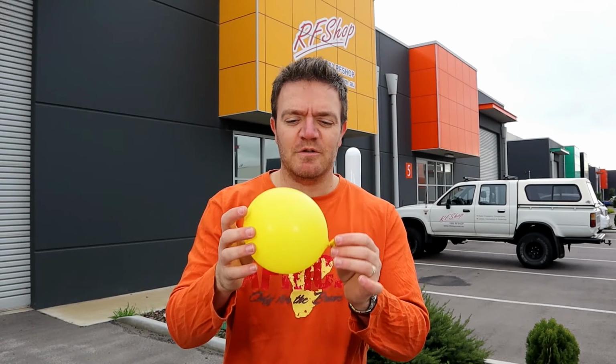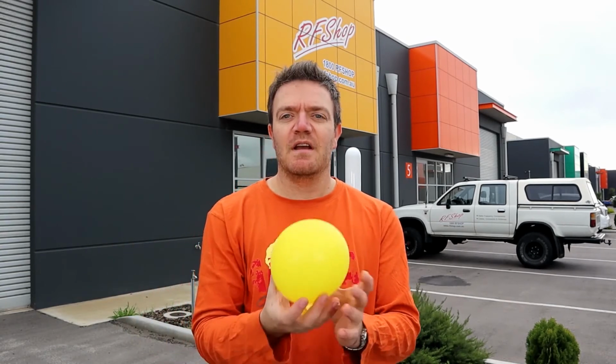But to explain really how it works in terms of the operation for a customer, let me have a look at this balloon. So when you look at antenna gain, the first thing is gain is not actually something that is gain that's more than nothing. It is just gain as in a relative measurement. So if I have something, that's my reference, which is like a round balloon. This is my reference, what I have. Then when you want to have more gain, it means that you do something different so that it actually works better in a specific direction. So let's say there's our reference point. That's an isotropic antenna, as we would call it. dBi is 0, so that's your reference, 0 reference.